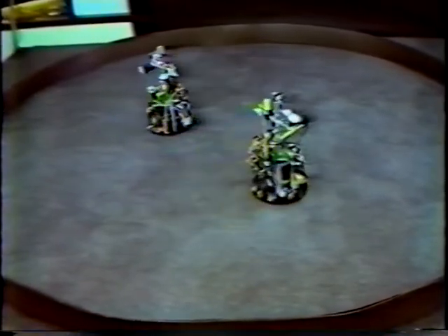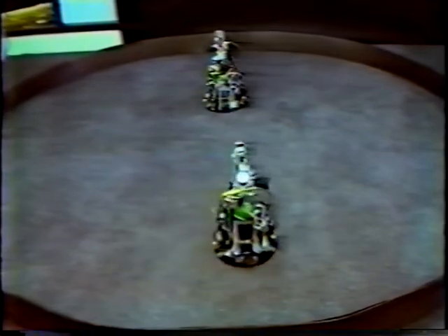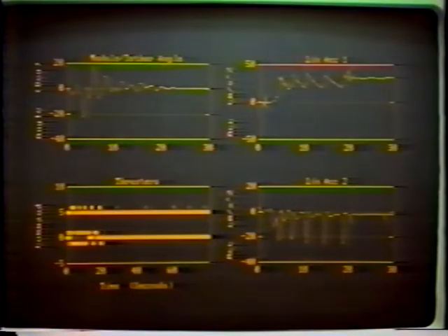There was very coarse control being used in this experiment so that you could see the effect. As the tether tension drops off, as reflected in the accelerometer measurement, a correction is made. A large pulse is given to speed the configuration up again. And this shows a plot of the results. On the upper right-hand plot, you see the sawtooth, which is the artificial gravity environment.